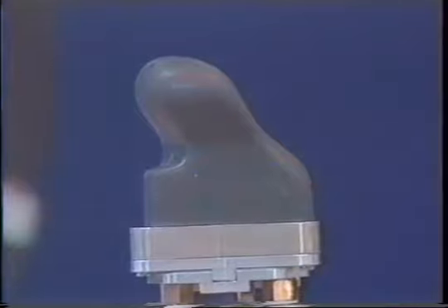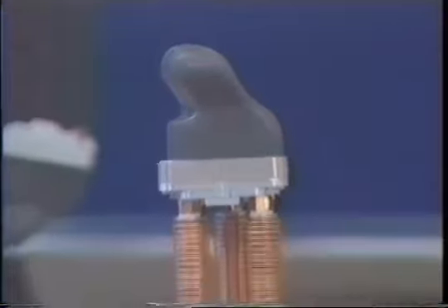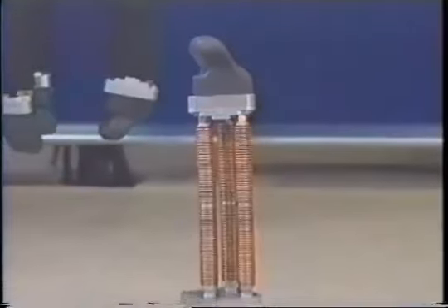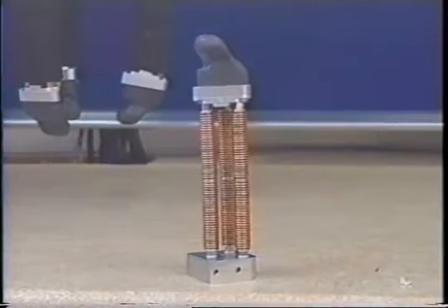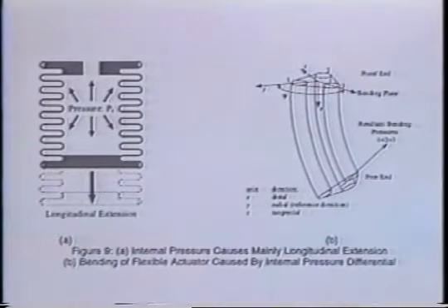The gripper fingers use an elephant's trunk flexible actuator comprising 3 phosphor bronze bellows. The bellows are mechanically linked and filled with hydraulic fluid. Controlled pressure variations in each bellow create bending moments, causing the finger to move with 3 degrees of freedom.